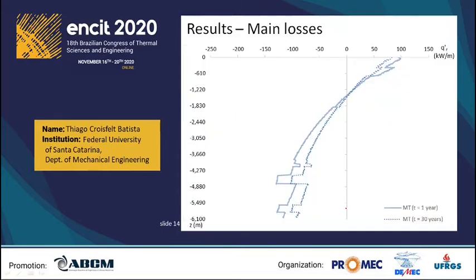Here we have the unidimensional heat rate profile. It presents some abrupt profile changes due to mesh discretization, which changes in the well diameter and the rock properties. This heat rate profile also changes a bit from 1 to 3 years of life cycle.